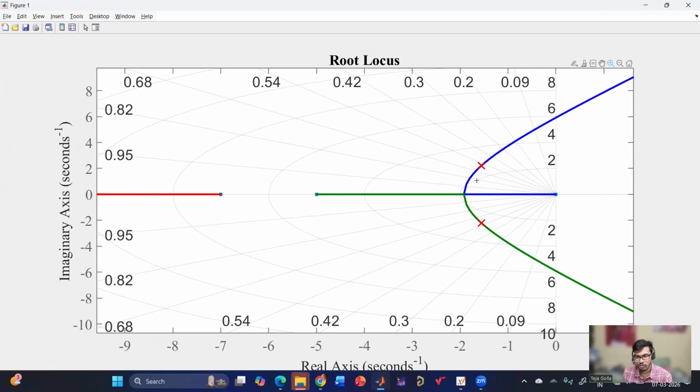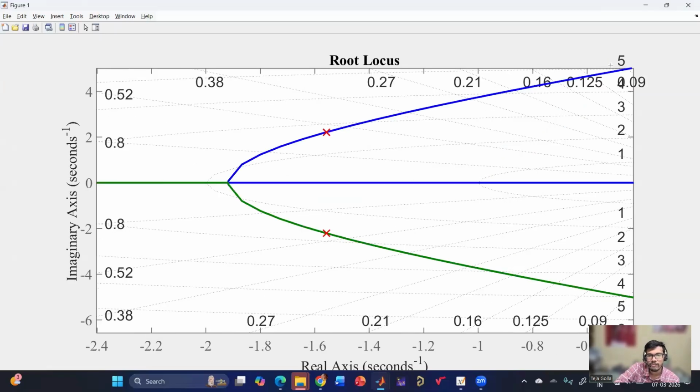Instead, we'll follow the step-by-step guidelines, and we'll see at the first instance that the root locus is passing through the desired pole location. So a simple gain K should be sufficient. Now let us see what the gain is. If I click at that point, I can get the gain. So let me click at that point precisely.